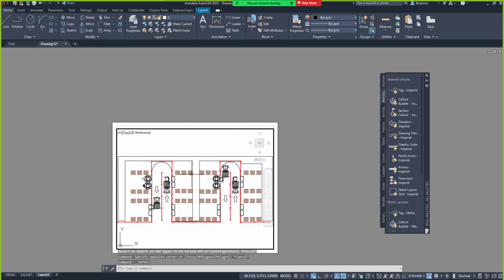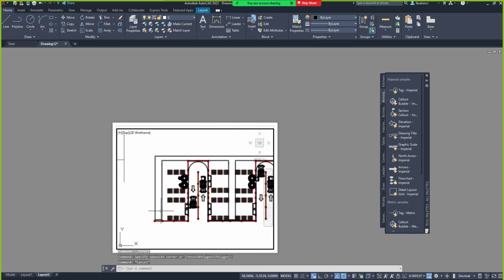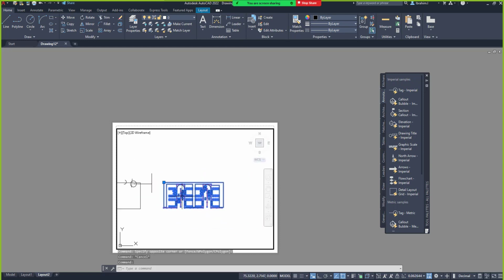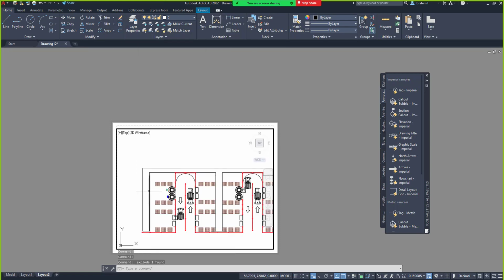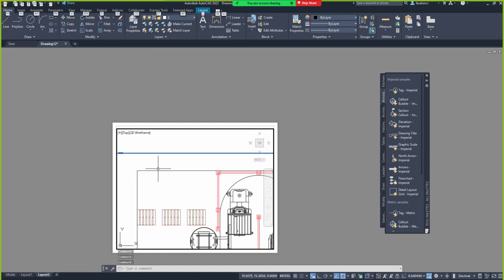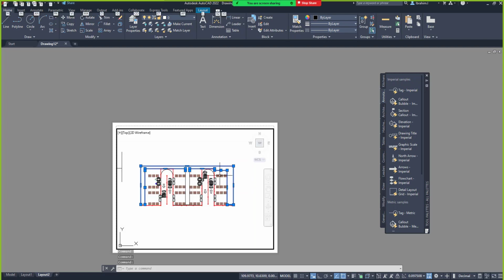Which are this other layer? I'll Ctrl Z. Go into my model, select the layers. Okay, this is a block, right? This is a block. I've converted this guy into a block. So what can we do? We can explode because we need availability to explode. I'll select this guy, go to this guy, select this other guy that is here. These ones here, they are all on layer 0, right?